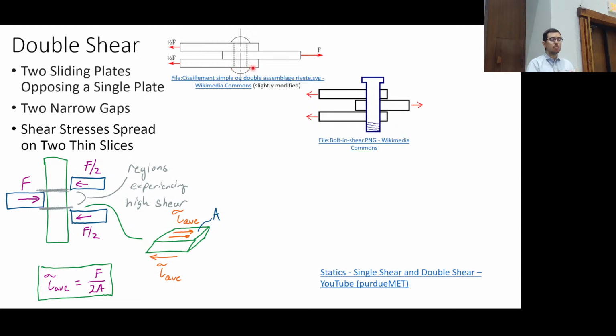Okay. Now, there's also friction in between them. If this is clamped, you'll study bolt tightening in design of mechanical components, and so one of the things that you also are trying to do, okay, is to make it so that there is frictional contact between these two, so that would relieve some of the shear, okay, on the bolt itself. Okay, is that clear? Right. This is the bolt. This is what's experiencing the shear. Right. But if I have these plates that go around and they're clamped together with a normal loading, then these plates also are able to take some of that force in terms of a frictional contact.